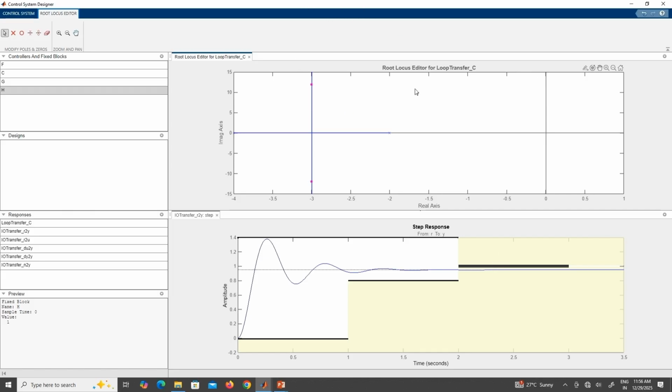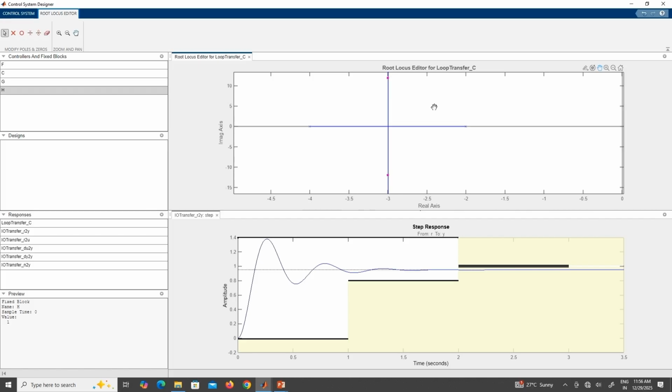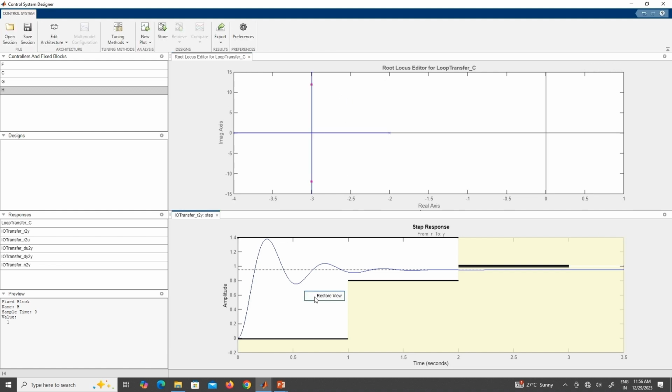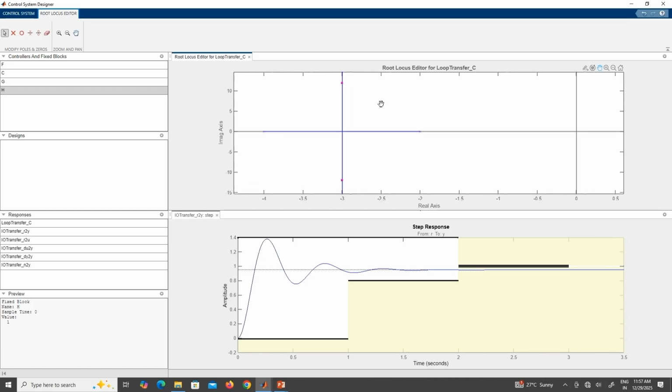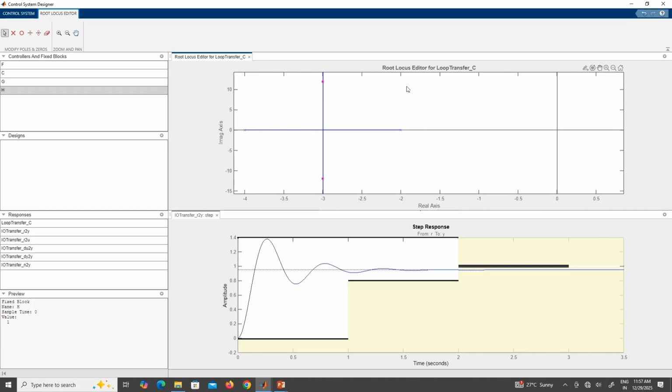Okay. So, now what you can do is, let us go to the root locus. Now, we will change the root locus. Now, how do I change the root locus? In the root locus also you can go ahead and right click first. Let me restore the views first, right click and restore the views. Now, on the root locus also you can put the design parameters that you have. Remember this hand is coming right now, you can see in the screen, you can go there and click on this. When you click on this hand, you can drag actually, if you left click and keep, you can change the position. I will just remove that now. This is the default mode, when the cursor is visible, where I have not chosen any of these tools actually.